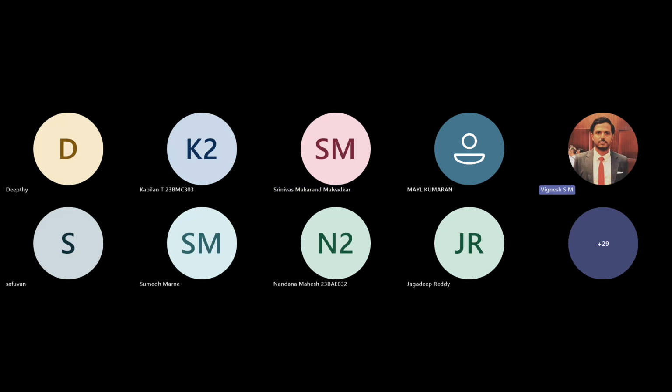The body should not be separated. For example, a propeller and an airframe should not be separated. It must have a connection. If it doesn't have a connection, both will be considered as two separate bodies. Okay, sir. So the connection can travel through different domains, right? The MRF domain that we created for the propeller, that is a domain, but the propeller needs to be connected to the shaft.